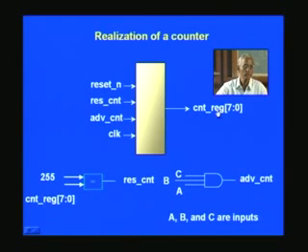Reg is to tell you, as a ready reckoner, that it is a register access. Register means a flip-flop, and this is the 8-bit flip-flop as such. So that's what is implied here. And we want to reset this counter when the counter value has gone to a particular value.